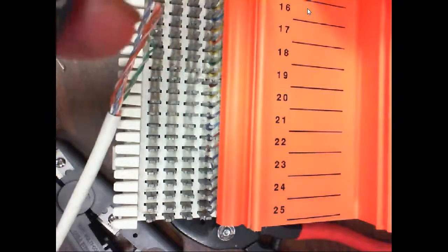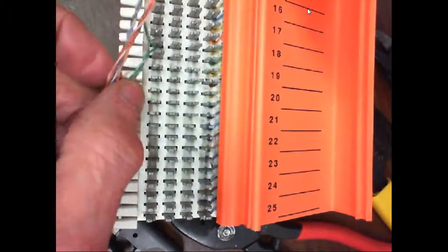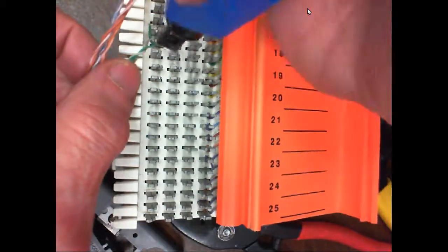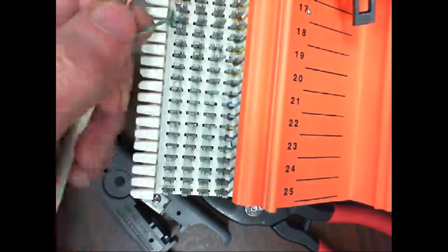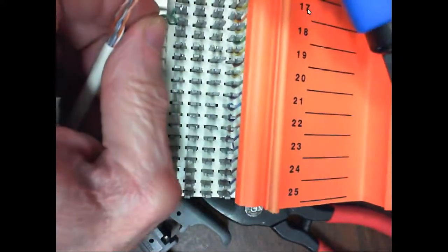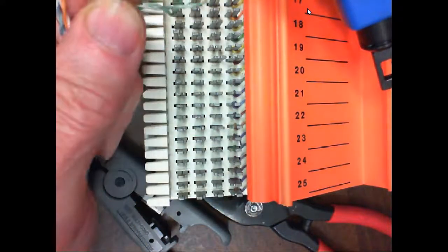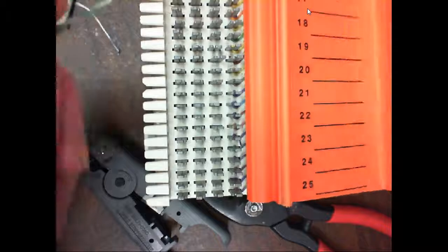And this would be for the 66 punch down. Everybody okay? Punch down block? That makes sense? You'll hear some people do it a couple times. Normally you don't have to do that. By the way, what's so nice on here, it actually strips that, and if you need to take it out, you can just grab it and pull it back out. So you don't have to strain relief this, right? You understand? Because you can pull that thing right back out.